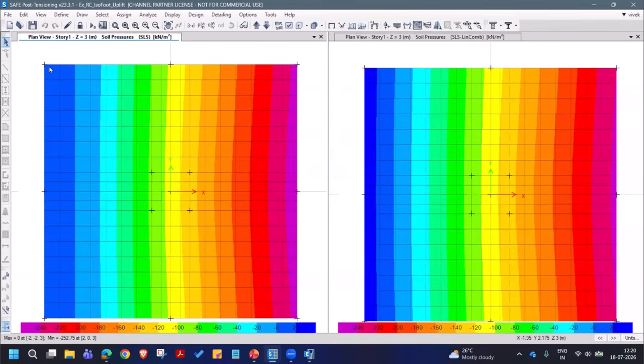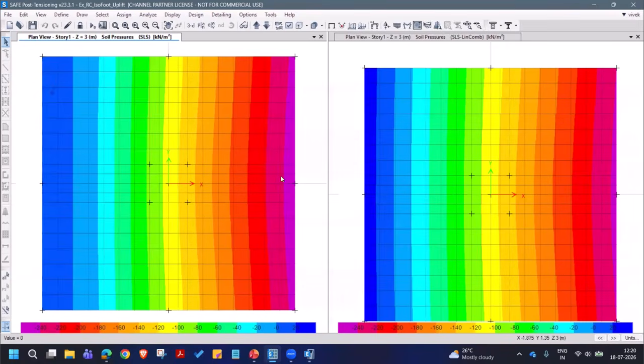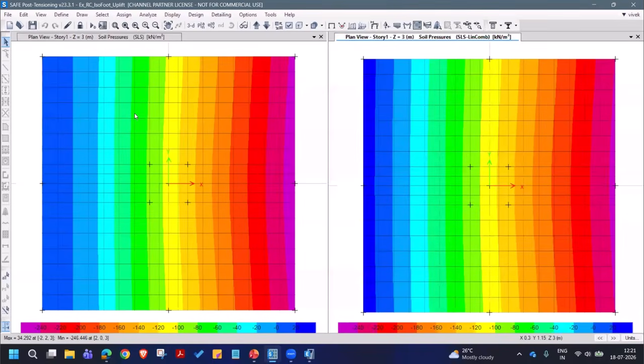Right, now we have performed the nonlinear case, and you can see the program could manage this for uplifting. There is no pressure, and the pressure here will be increasing accordingly. These nonlinear cases are already converted for the design combination. You can directly perform the design of this. So there isn't much for the user engineer to do, but if you want, you can modify this further. But the program is capable of handling this uplift.